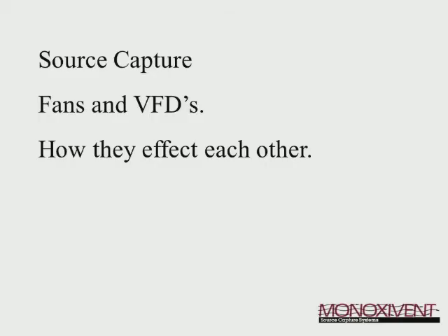All right, so source capture fans and VFDs and how they affect each other. More and more recently, we get asked about adding VFDs to our system. Certainly that's up to the engineer specifying and designing the project. Bottom line, for me personally, if you're doing 1 or 2 or maybe even up to 5 hose reels, that seems to be a bit of a waste of time. It would be difficult to regain the payback on that. Beyond that, maybe 8, 10, then maybe it's worth it. But some things to think about.